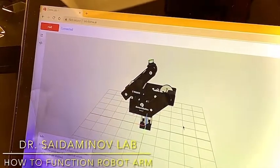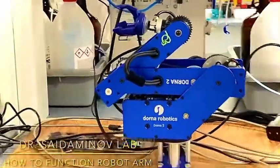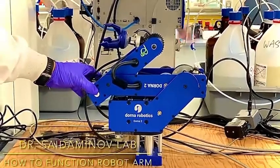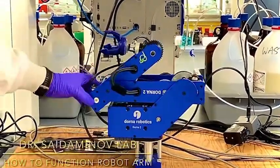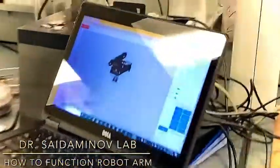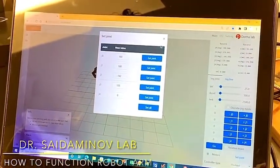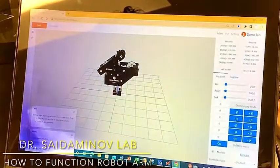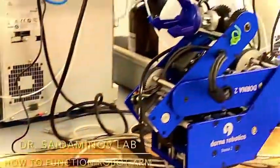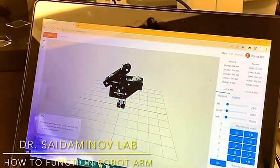But before everything, we need to set the robot arm to the zero position that we call the home position. This is the shape that it should be, exactly like this, and then we need to save it. For that, we go to set joint and set all. Once it is set all, you should see the image of the robot arm exactly similar to what we are seeing there. Then we can command it to make sure that everything is good.